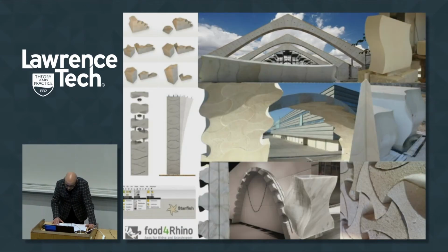And so a new family of stereotomic vaults set out from the typical interlocking of the ashlar of the flat one can be formalized by using the deformation by folding technique already exposed. This perspective aims to solve some of the most important theoretical issues related to the realization of vaulted spaces, improving mutual anchorage and therefore the friction among the ashlar of the vaulted system, reducing the wall thickness,